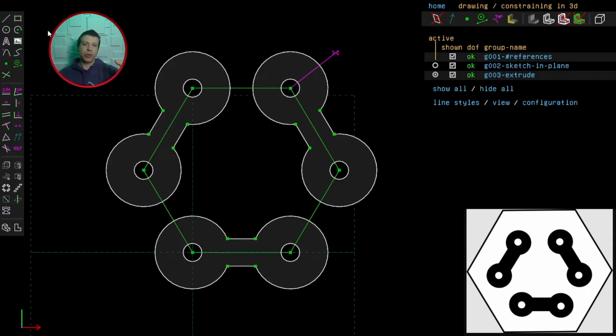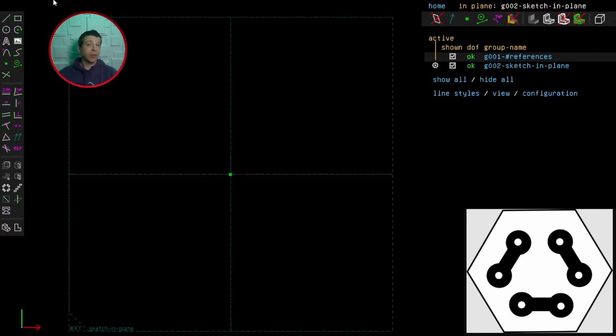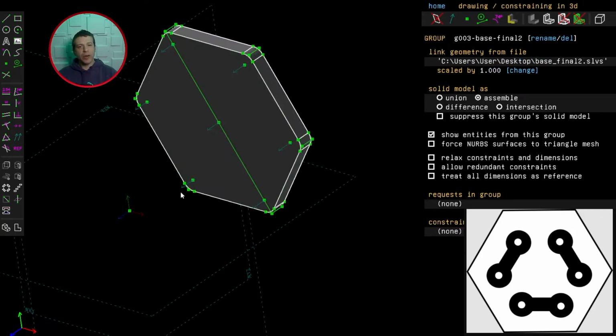But we need to make sure that the wires position properly relative to the base. And let's do that now. Go to File, click New. At the menu bar, find New Group. Click on it and go down to Link Assemble. A pop-up window will appear, so I'll click Base. These arrows pointing out from the points are normal lines.